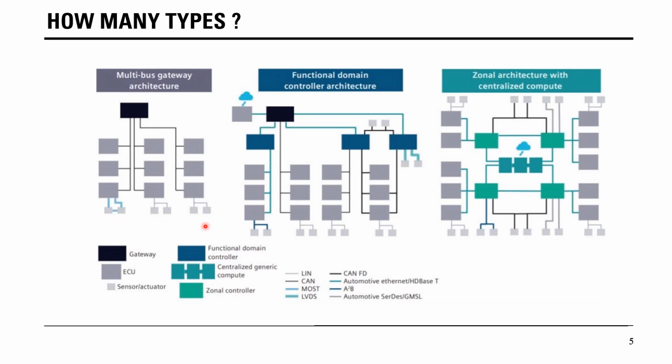Coming to the basic architecture, we have a gateway ECU and each peripheral ECU, connected to different small ECUs or sensors communicating in between, and all together communicating on a single network, depending on only one communication protocol. If you see these black lines, they are connected by either CAN or CAN-FD. So we are just using the CAN or CAN-FD protocol to communicate between the gateway and different ECUs. Also, the ECUs connected internally together form a complex network, I would say.